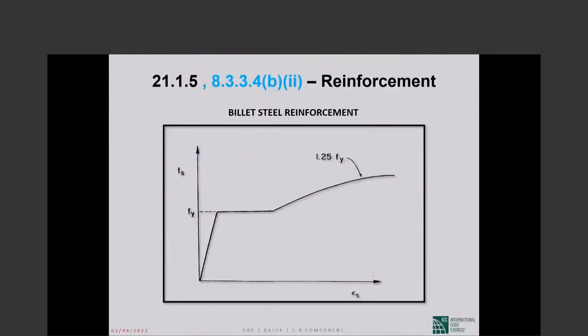2020. The third supplemental requirement is that the actual tensile strength, when you test your reinforcing bar specimens, shall not be any lower than 125% of the actual yield strength of the reinforcement. Okay?